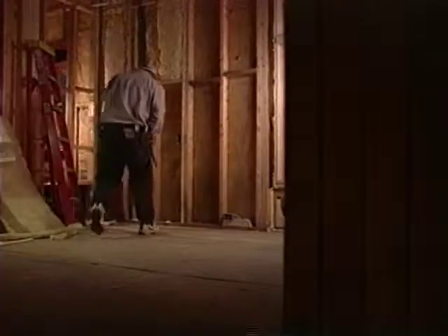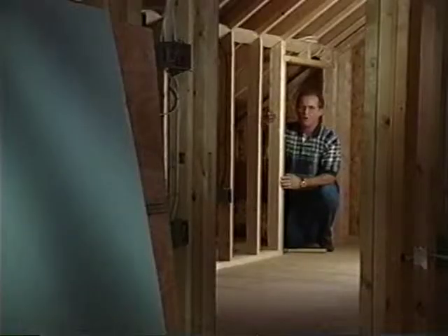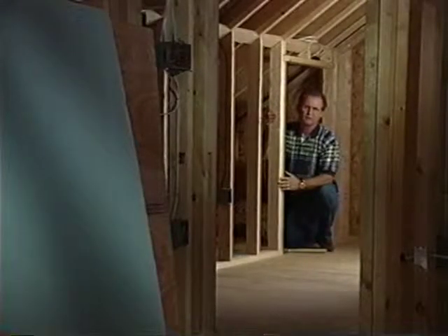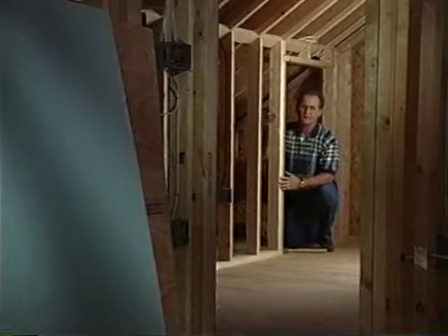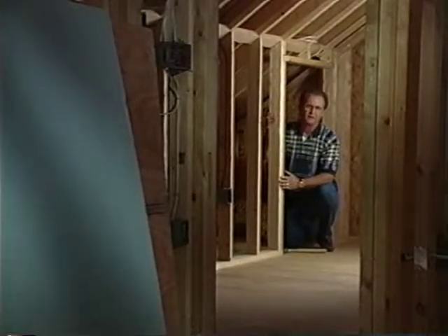As an insulation and air sealing specialist, it's your job to spot breaks in the air barrier and seal them. Some of those gaps are harder to notice than others. Knee walls in bonus rooms and cathedralized rooms are large contributors to comfort complaints. You as an insulation installer can certainly help this tremendously by taking insulated sheathing and installing it on the back side of the wall.